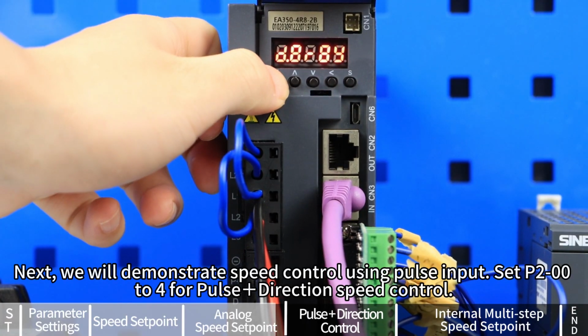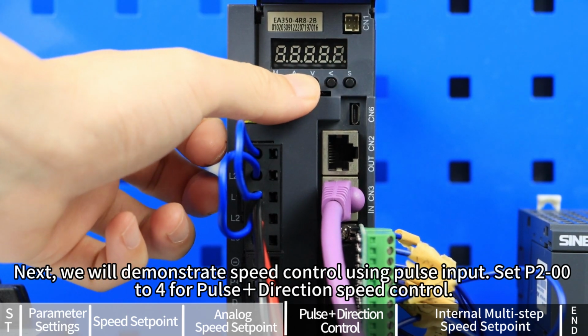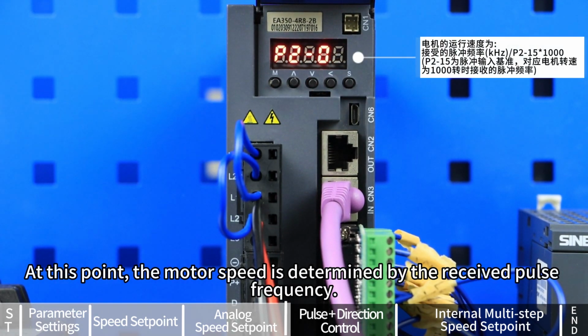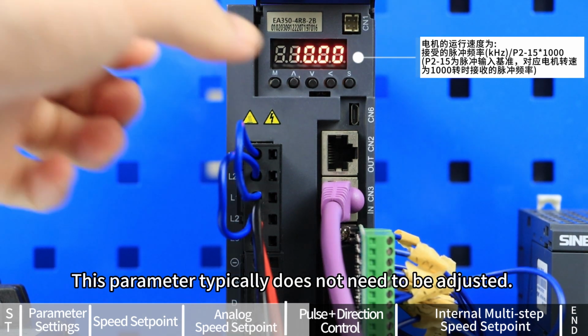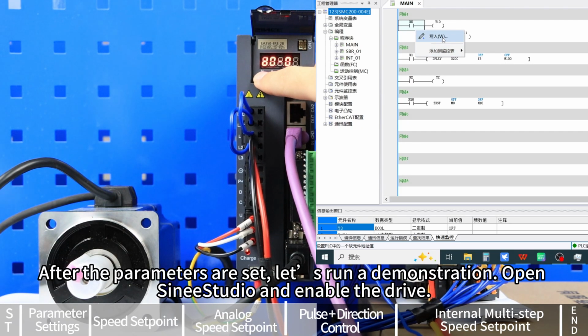Next, we will demonstrate speed control using pulse input. Set P200 to 4 for pulse, direction speed control. At this point, the motor speed is determined by the received pulse frequency. In addition, it is related to P215, the pulse input reference, which is set to 10 kHz by default. This parameter typically does not need to be adjusted.